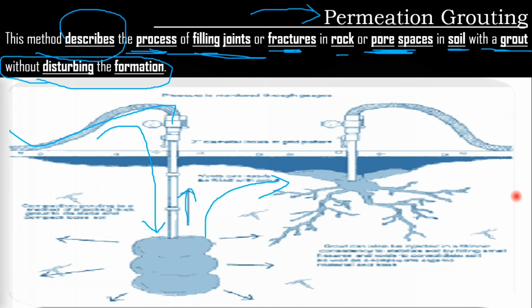So whenever we face any crack or any pore in between soil or in between rock particles, that will be totally filled with this grouting process. Okay, so just clear one thing in your mind: the entire process goes only with gravity. We do not provide any pressure or any force to fill out these pores or fractures or joints. Okay, so it is represented as permeation grouting.